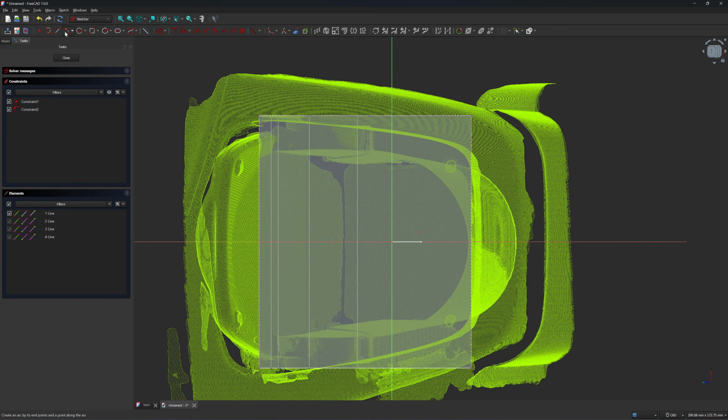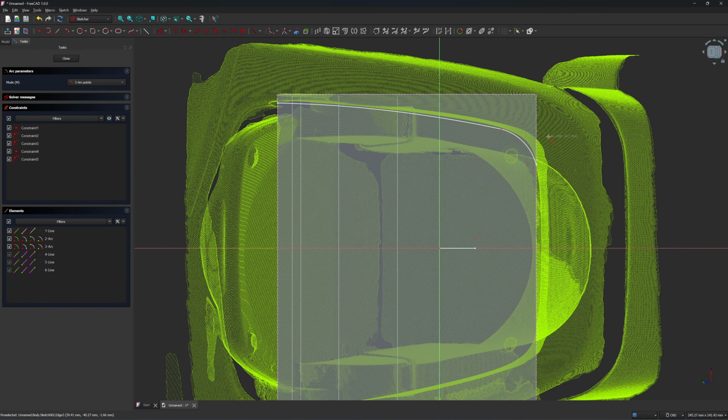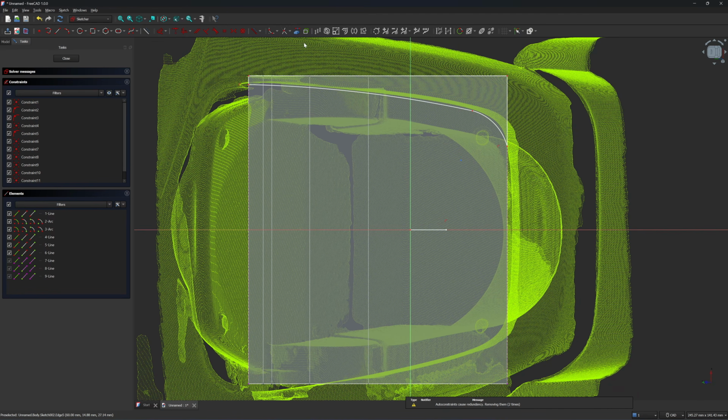And next I'm going to create a cutting line using arc. I make it a little bit smaller like this because we're gonna cut it, so we need to make a closed profile. I make a line here, second line and third line, and then I should be able to select this and mirror it to the other side like so.